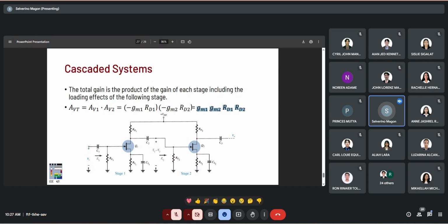If we want an in-phase amplification, if we don't want the signal inversion, we can cascade an even number of amplifiers and it will result in a positive gain value. It will counter the inversion of the common source characteristics. Same as in the case of BJT, if we want a non-inverting amplifier, we can cascade an even number of common emitter amplifiers. Okay, so hopefully that's the insight that you can remember out of these calculations.